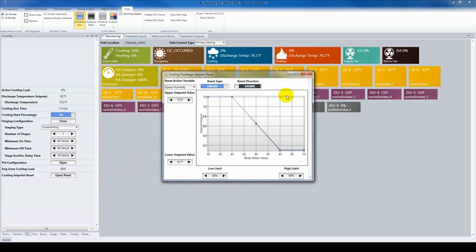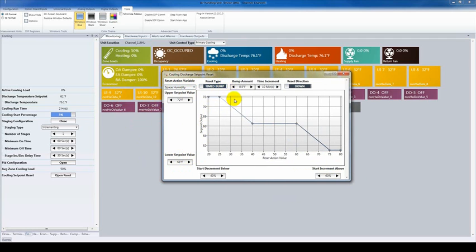And you can do supply temperature resets for both cooling and heating, and they're very easy to work with. What are you going to reset it against? What's the important variable? Just click from the drop-down menu. Is it going to be terminal load, space temperature, return temperature, space humidity, outdoor temperature? You choose. Just click and configure. Your set points upper and lower are here. Your low limits and high limits are here. You can determine whether it's going to be a linear reset or a timed bump reset. More on that in the iNet literature at the inetsupervisor.com website. But you can see that it's very intuitive. Any competent HVAC technician can easily work with this system.